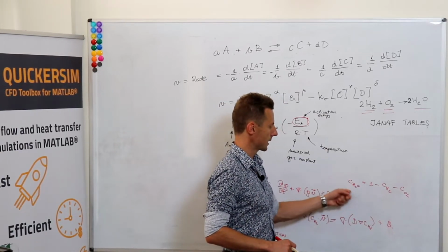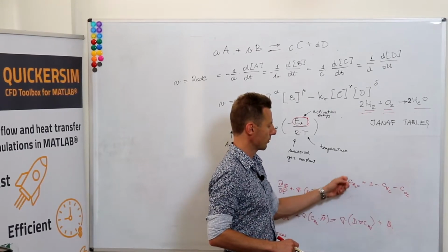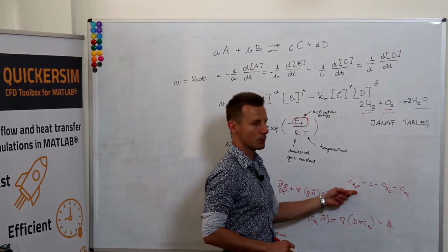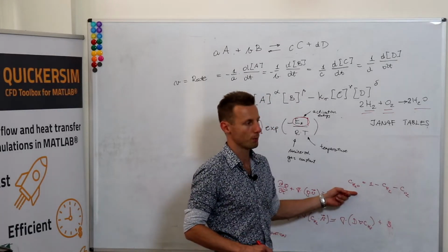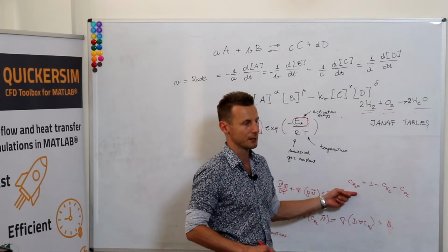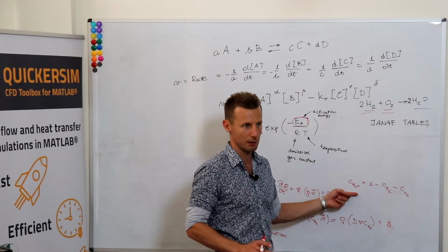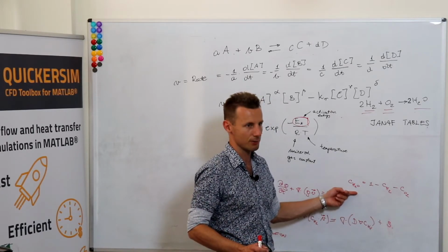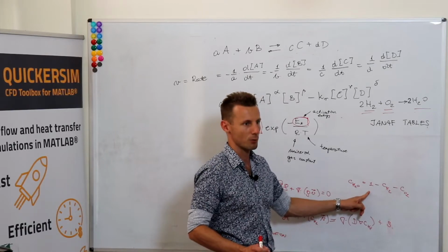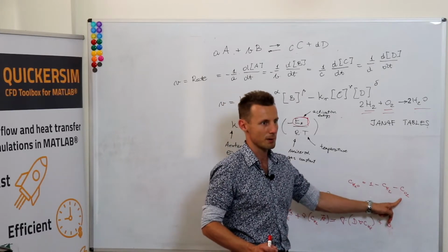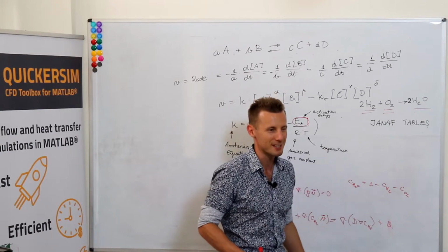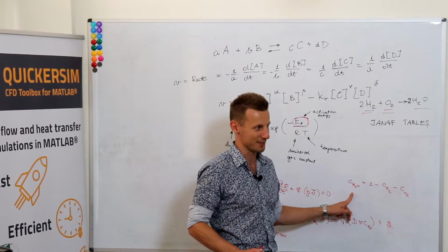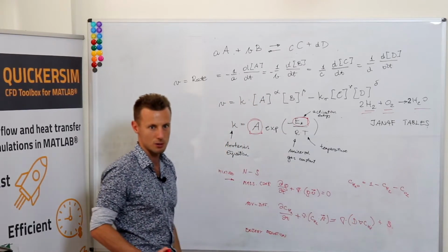Yeah, and take the one of which you've got the largest amount in your mixture, because if you select it improperly, then you might run into numerical problems by having it almost zero in the physical world. Almost zero in the physical world means that if you've got some numerical errors, you might have 1 minus too much, and that's already a bit less than 0. And it doesn't bring anything good to the physics, having negative concentrations.